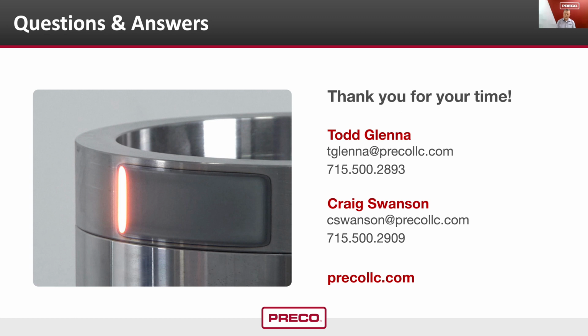There are instances where we have ID of tubes, for example, where people ask us to heat treat or clad, and that is possible. Depending on the size of the ID and the depth of what needs to be heat treated, they do make specialty heads to get into the ID for both heat treating and cladding that we have used. If it's a large enough ID, we can come in at an angle of incidence.